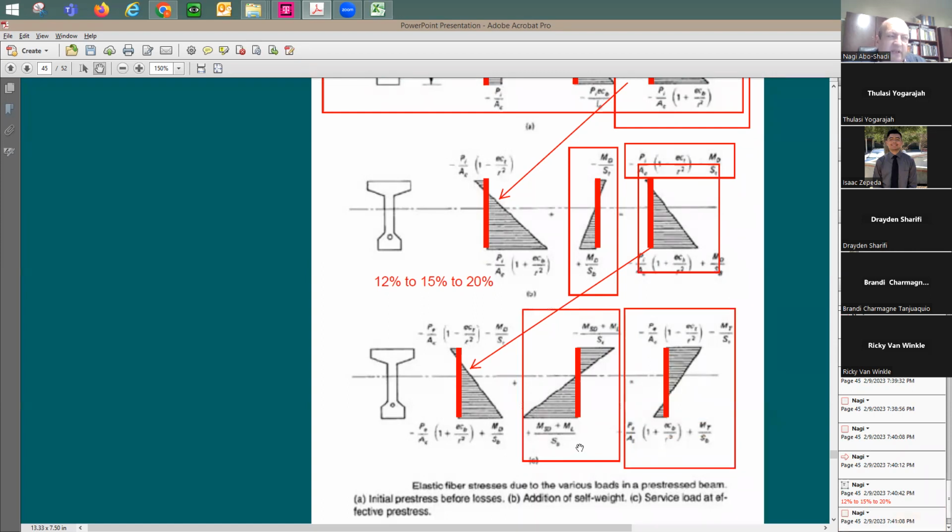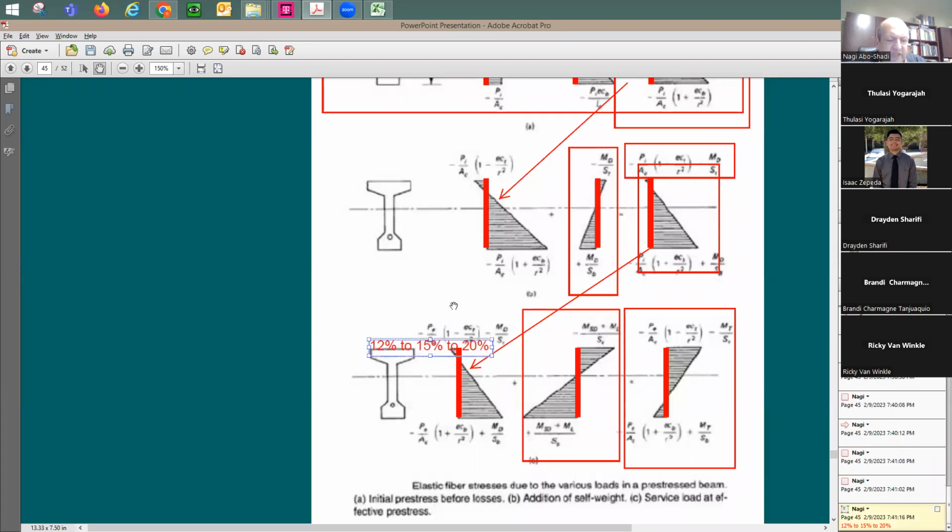So you cannot really take the effective stress from the beginning, PI, and just add all the stresses to each other. You need to look at the steps and what happened to the stress distribution. And then you need also to understand that at this stage of loading, it is true that you have kind of some fresh concrete at the time of applying the stresses. The concrete is not 100%. So the f'c is not really at 28 days, and most likely maybe it's going to be at 7 days or maybe 10 days. Sometimes at 4 days, depending on the curing process or technique that they use.